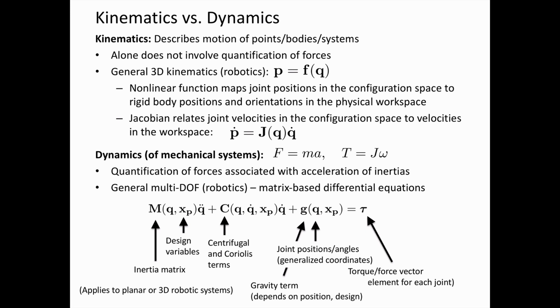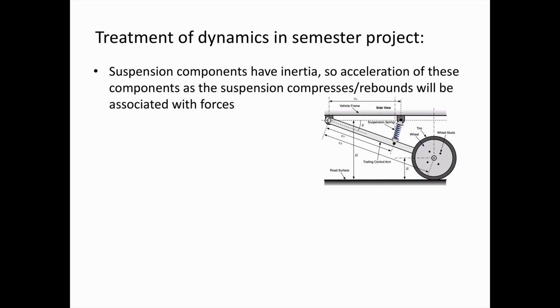So key takeaway, kinematics focuses on motion. Dynamics brings in force analysis that's associated with acceleration. So in this semester project, how are we going to treat dynamics? In a real suspension, the components have inertia. And as the suspension moves, as it is compressed or as it rebounds, these components are going to experience acceleration. And because of this acceleration, there are going to be forces associated with that.